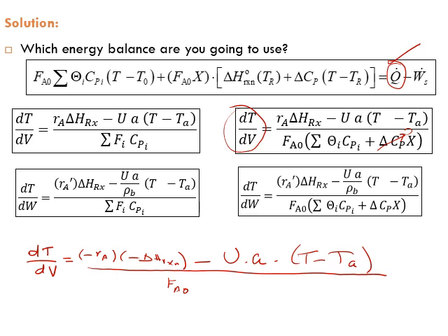We said we can call this CP naught, right? And in this case, how many thetas do we have? Well, it depends on how many species we have in the feed. We have 2 species, so basically we have 2 thetas times CP naught, where CP naught equals CPA plus theta I times CPI, because we have 2 species in the feed, A and I. Theta A is 1.